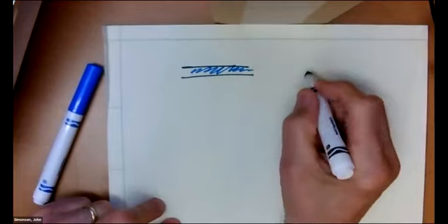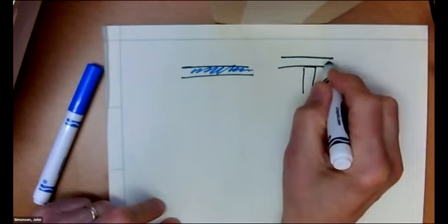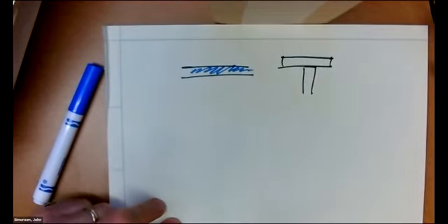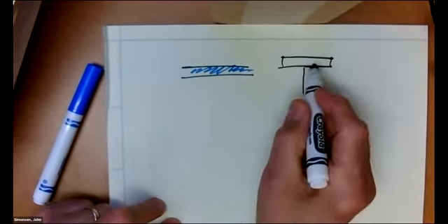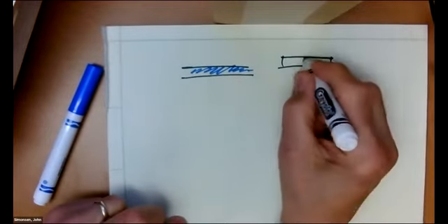But if you have a situation where you want to, for example, glue a 2x4 to a joist or a header or something like that, now using glue doesn't make a whole lot of sense. The reason for this is because the bond strength of glue or adhesives per unit area is much, much smaller than mechanical fasteners, like a nail or a bolt, right?